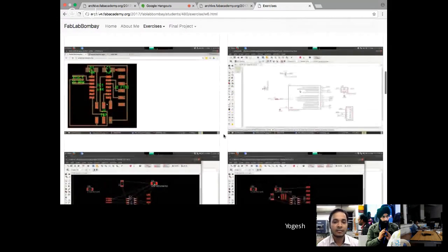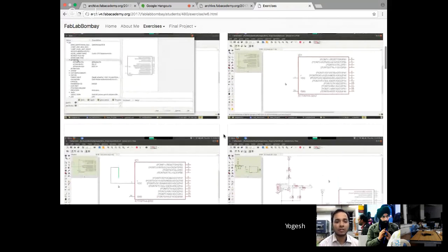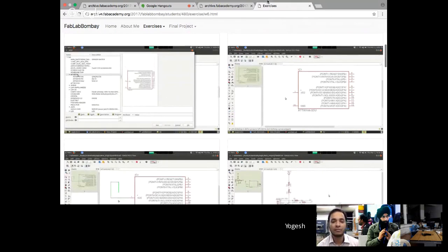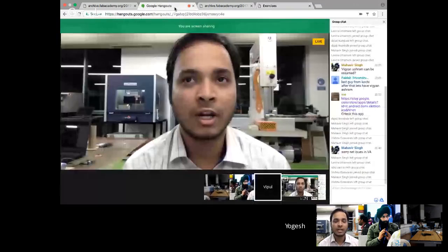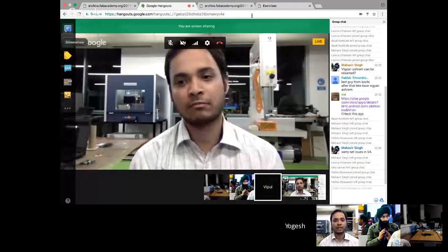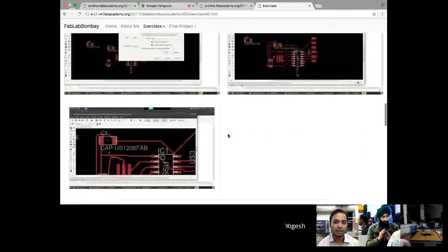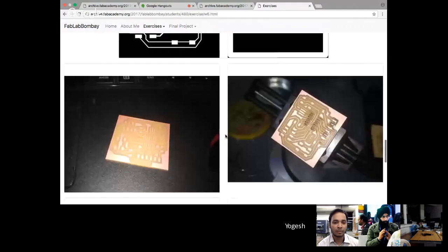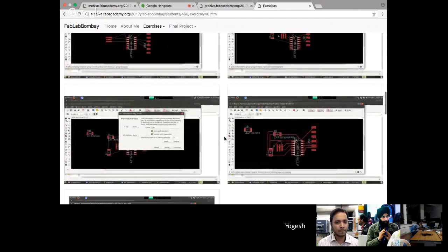When I created the first sketch using auto routing and put it into Fab Modules, I found that there are some places where it is not cutting, meaning it is leaving traces where it should not. So I tweaked the board layout manually, and when I was satisfied and Fab Modules showed that it is cutting, we milled that board. One more screenshot you have to add is of the DRC.